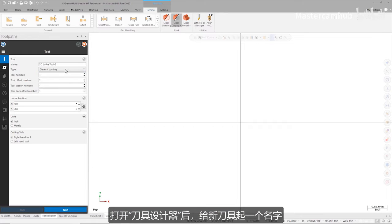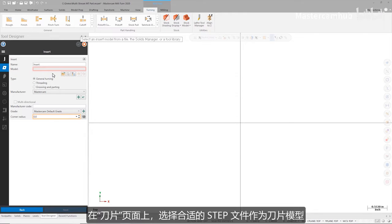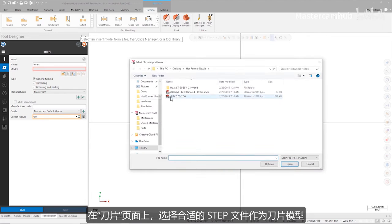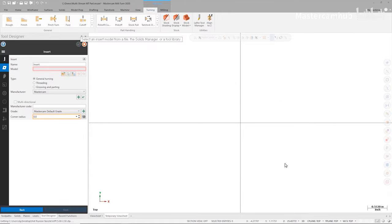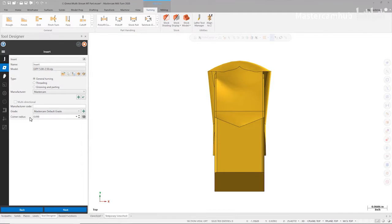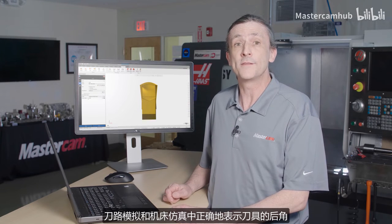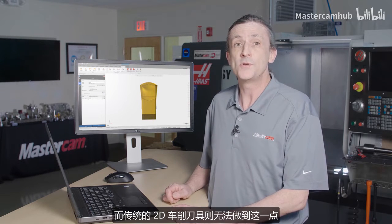Once the tool designer opens, I need to give the new tool a name, select the type of tool from the tool type dropdown, and set an offset number. On the insert page, I need to select the STEP file that I want to use for the shape of my insert. And I need to define the corner radius, which I can enter manually or select from the model. Using a 3D insert means that Mastercam can properly represent the relief angle of the cutter in backplot and simulation, which you can't do with traditional 2D lathe tools.